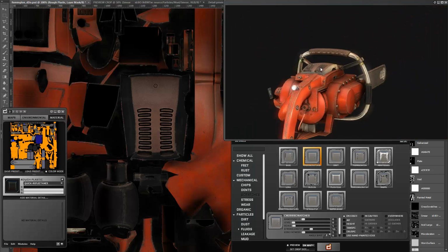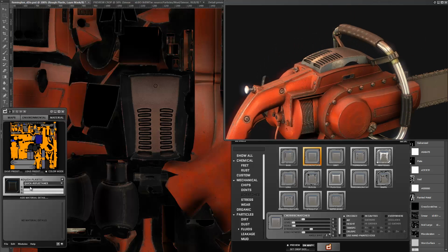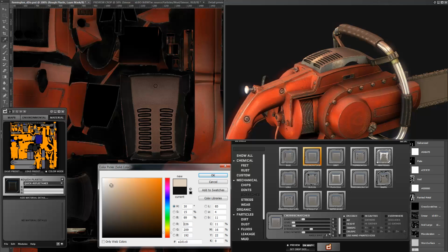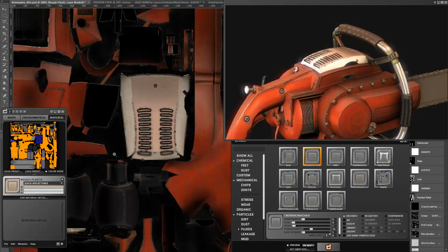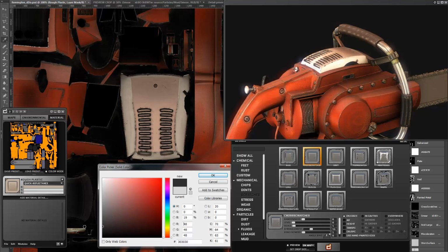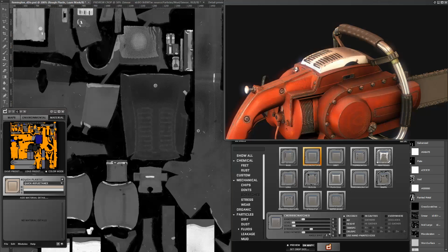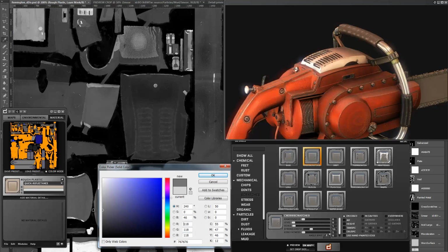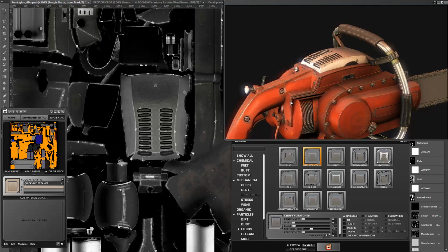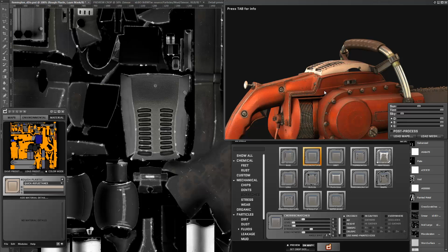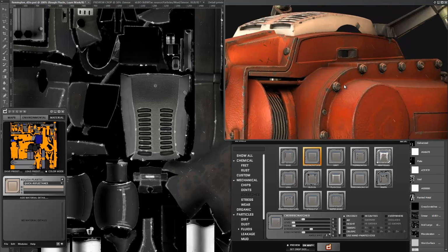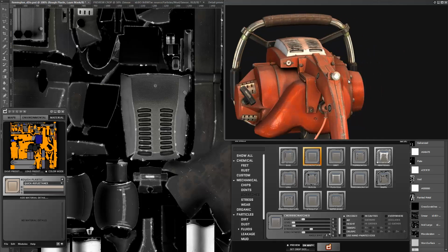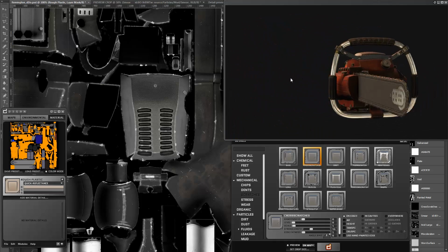It's already looking a lot better, but it's way too shiny and it's too dark. I want it to be a bit more plasticky. So I'm gonna make this look a bit beige in the diffuse. I'm gonna reduce the glossiness quite a bit, and decrease the specular to around 50%. There we go. Remove the post-processing to avoid the blur and bloom. It's already starting to look really cool, if you ask me. Got some pretty nice material separation.